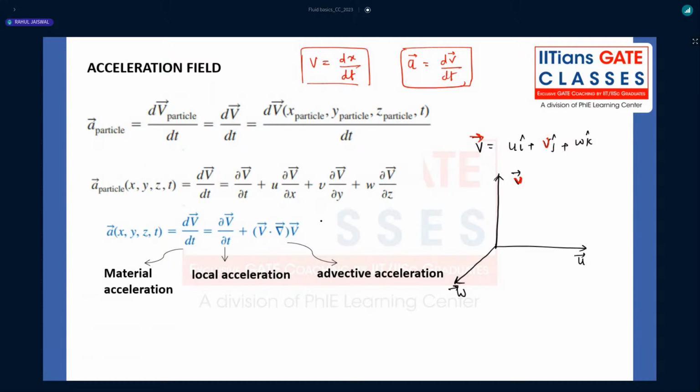In vector calculus, the particular mathematics subject, if you are representing this in a vector format, we can write like this. Acceleration can be written as, no need to worry, I will prove that, dou v by dou t plus v dot del. Del is nothing but the del operator. This can be written as i cap dou by dou x, j cap dou by dou y, k cap dou by dou z. Anyone know about the del operator?